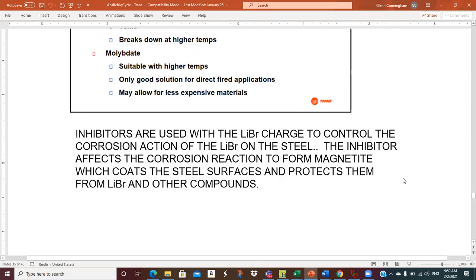It's interesting, in the power plant, magnetite can build up in the steam lines, and it's hard, and it doesn't give. So if they take a unit out of service, the steam lines all shrink a little bit because they cool down, and that causes a compressive stress on the magnetite, which cracks it.